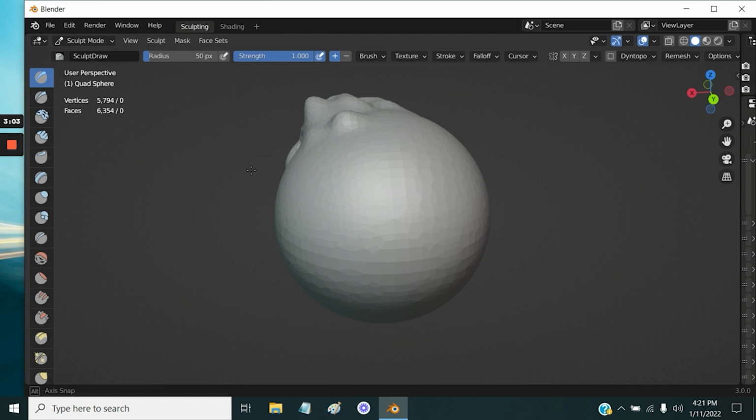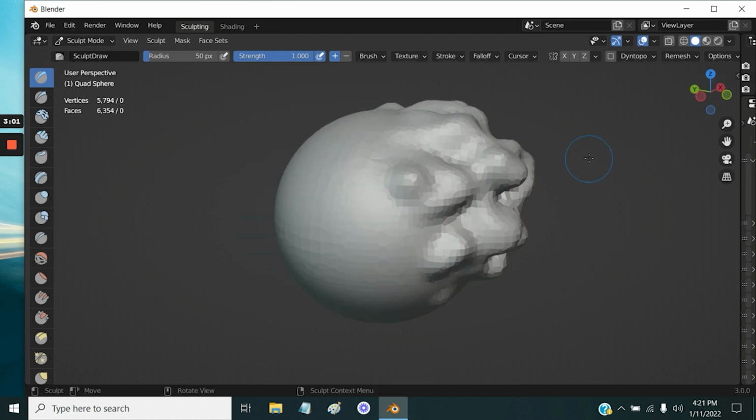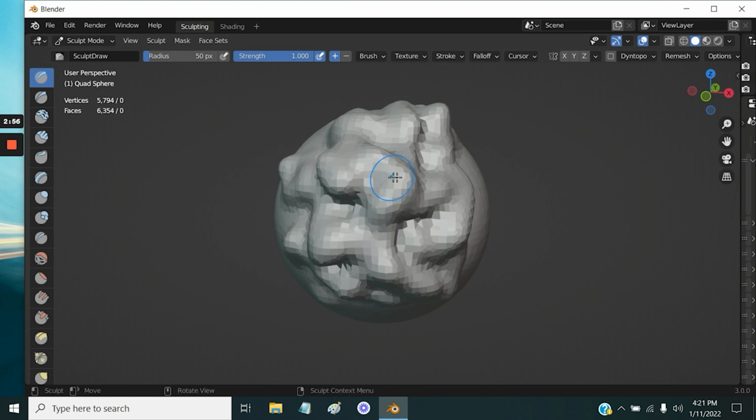And what adaptivity tries to do is move your vertices from where there's less detail to places where there's a bit more. Perhaps it wasn't quite as apparent in this example, but that's what it tries to do. If you have a lot of flat edges and those edges have a lot of vertices to them, the vertices will be removed from those flat edges and pushed to the curvy areas. So that's Remesh. I'm going to go ahead and undo.